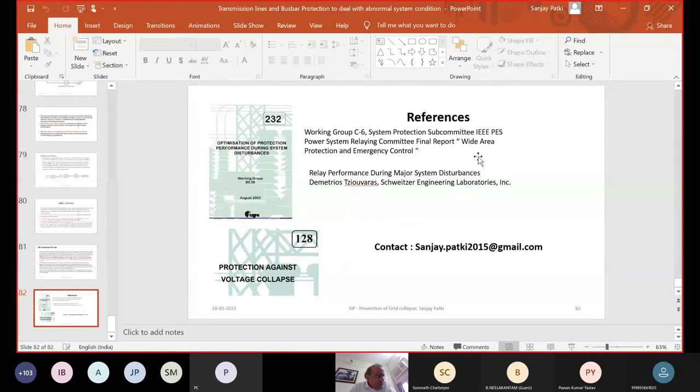Yes, sir. See, it is not mandated for 132 kV, but nowadays, depending on the criticality of that 132 kV line, if that line is critical, you should always go for a redundant protection scheme. And with numerical relays, you have a multifunction relay. So nowadays, it's very easy to provide main 1 and main 2 all in one protection, so that backup can also be included in that.